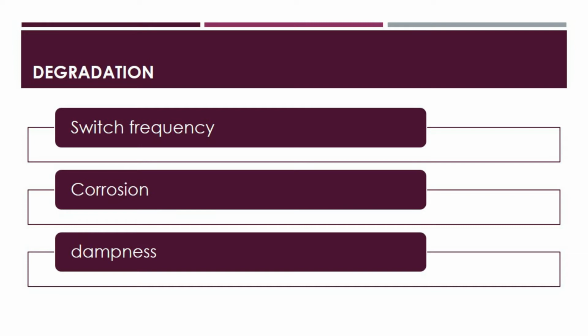In the absence of specific difficulties, it is standard industry practice to run distribution switchgear until it reaches end of life, right before failure. A variety of intervention measures are used on a regular basis to extend the life of these assets and reduce in-service failures. So for example, inspection with thermographic analysis and cleaning with CO2 for air-insulated switchgear, etc. If faults or deficiencies are discovered during the inspection, the afflicted component can typically be replaced or fixed rather than having the switchgear completely replaced.